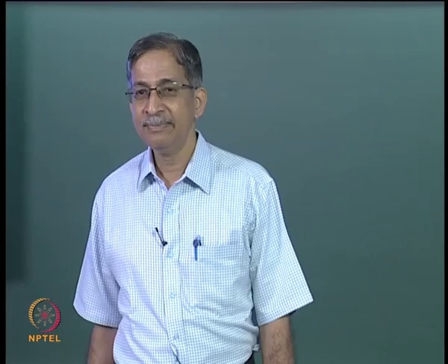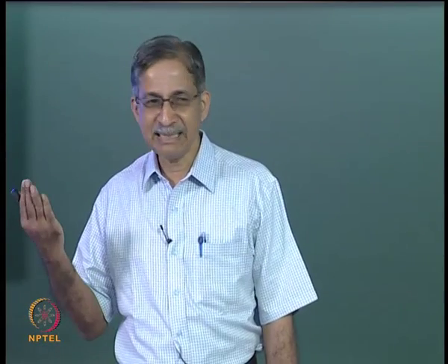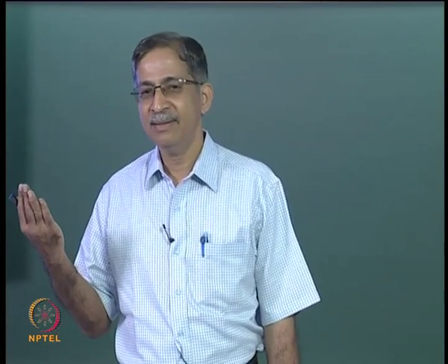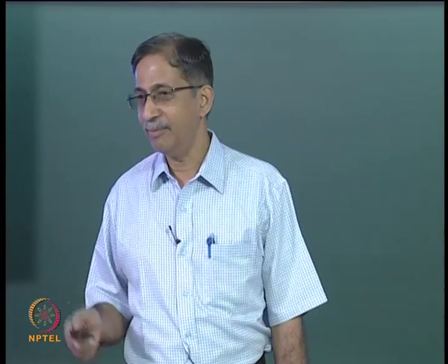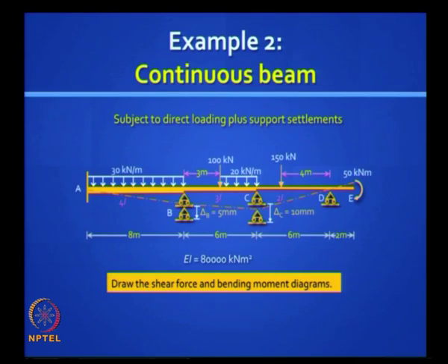What is the first thing we will do? First we will simplify our work. So we will get rid of the overhang because it will unnecessarily bring in more coordinates. We don't want that, we want to minimize our work, so you do that. But still, even after doing that, what is the degree of static indeterminacy? 3, right? Just think of the primary structure.